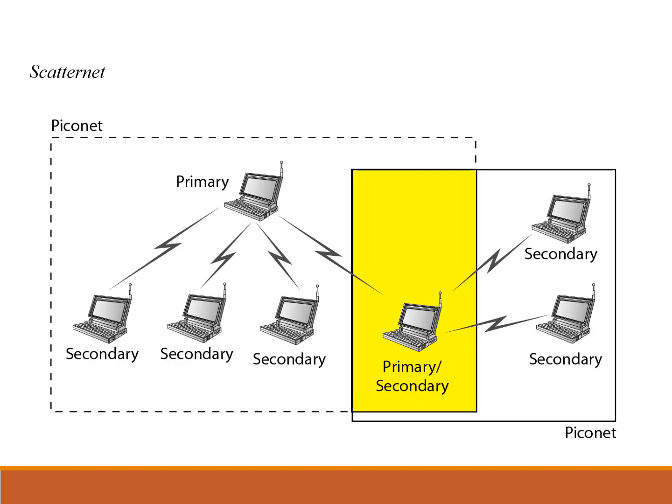See here, this is a multi-slave, and then it is called a scatternet. Several piconets can be established and linked together in a topology called a scatternet. In a scatternet, some devices are common to more than one piconet. Only one piconet can be active at a time. Different piconets in a scatternet can participate through time division multiplexing, that is TDM, sharing a common channel.